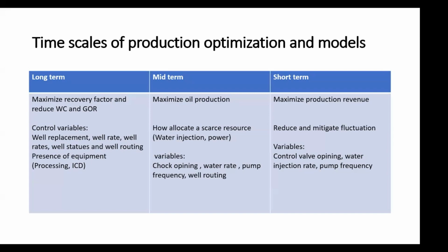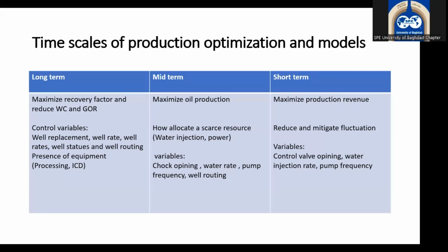If we change a well routing based on the different separator pressure, we will get different performance on the well. Or designing ICD, inflow control device, or inflow control valve, to get a better production profile and reduce the water cut.